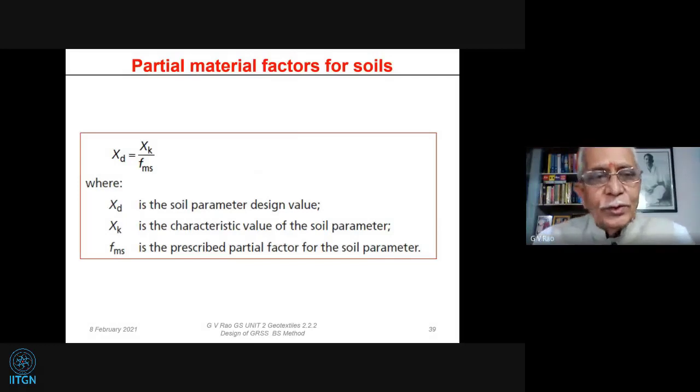So we continue the presentation on the British Standard Code for reinforced soils very broadly. So we said there are two things which make it very specific. One is of course the limit state method of design. The other thing, as I have mentioned and we will continue today, is that there are two basic methods which are different. One is called the tieback wedge method, the other is called the coherent gravity method. I think today, if time permits, we will be able to go through that also.